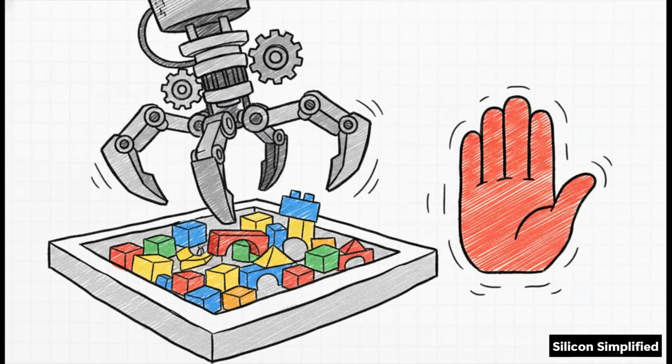Okay, so let's break down the first piece. Your main sequence logic lives right inside the body task, and this is automatically executed via the start method. This is your user-defined sandbox. But, and this is a huge but, why should you never call this method directly? Well, it's because the UVM phasing mechanism and the start method handle all the necessary pre- and post-execution callbacks entirely automatically. If you call body manually, you're bypassing critical framework steps, which leads to nasty sequencer deadlocks and just bizarre simulation errors. So definitely don't do that.